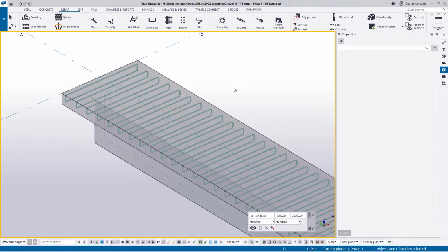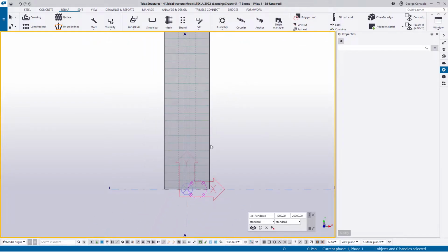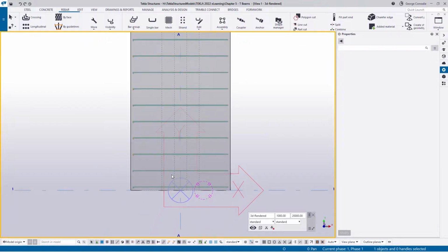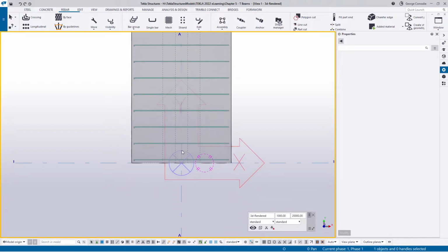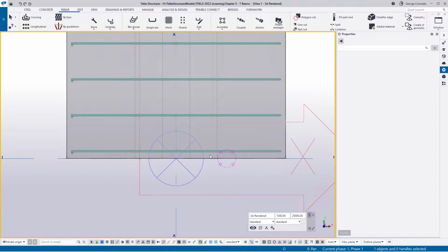Now, they would not necessarily use a ligature in a beam like that, because they need to access the web to insert the reinforcement, and if they have to feed it in from the side, you'll probably end up with a lot of angry people. So what we normally do is split this one on the top and leave the top bar out so we can deal with the ones on the bottom.